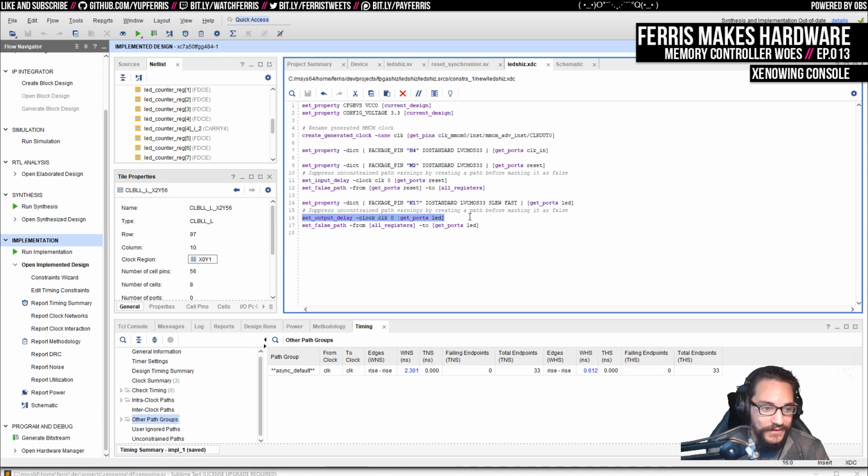It always reported errors in the timing because I didn't know if those were benign or not, because they might be. A lot of the times when the tools are doing timing analysis, they're being conservative. They might do timing analysis assuming the chip is running at like beyond its regular operating temperatures. If it's too cold or it's too hot, or you have some weird process variation, and it's going to try and simulate all that, because of course this stuff changes with temperature and everything, and also so it's kind of complicated.